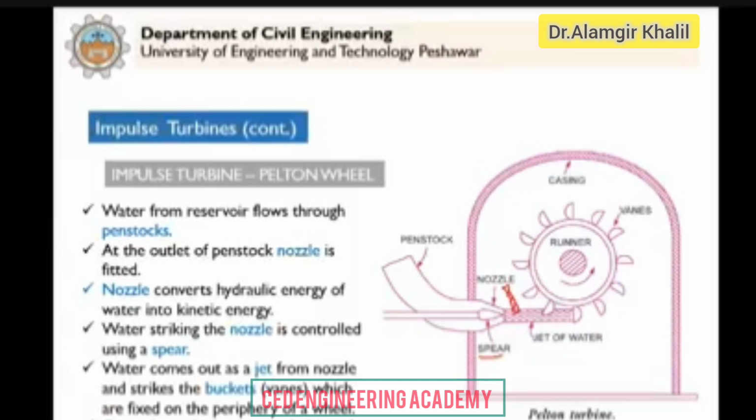You see, it can come here and this water will fall down, and a reduced quantity will strike the vanes or blades. This is how we can control the speed of the turbine. This arrangement we call a jet deflector. So we deflect the jet so that a reduced quantity of water can strike, and hence we can control the speed of the turbine. This is a second arrangement.